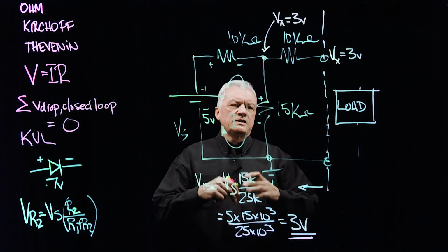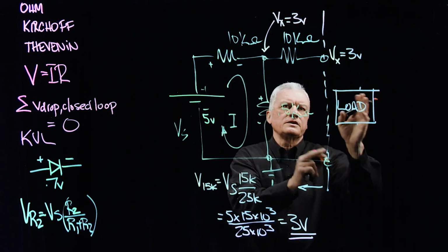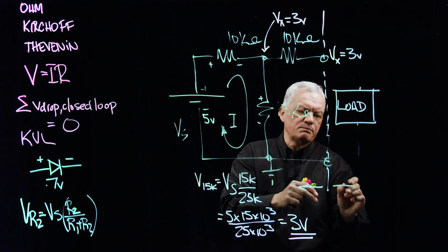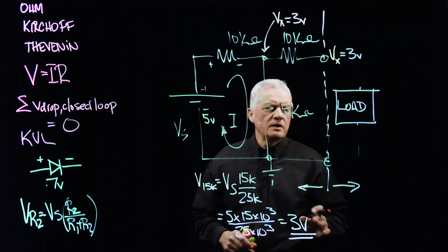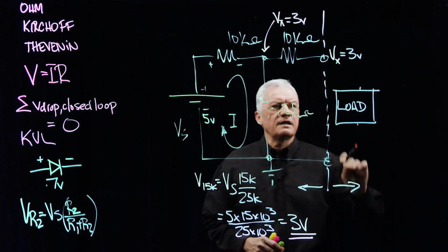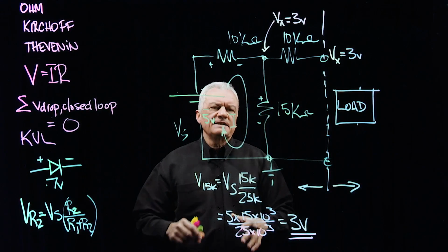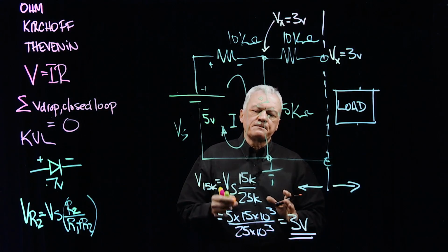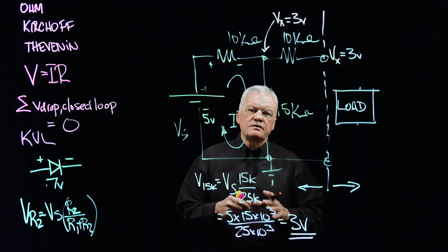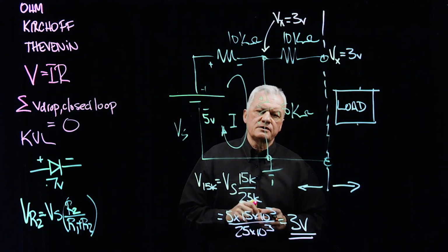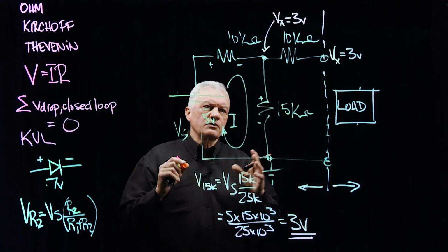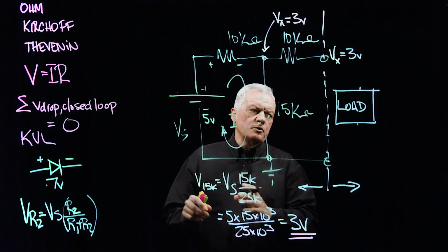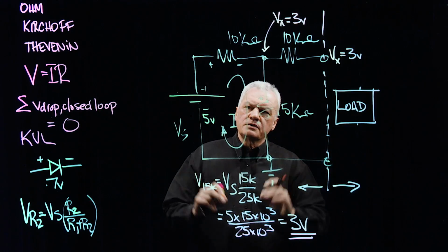He says, it's one thing to know what is the voltage presented outside of this black box, okay? What is the voltage presented to the load outside of this black box? But internal to the box, there is an internal resistance. And as current is drawn, there will be a voltage drop across the internal resistance. So what he tried to do is create a model of not only the voltage source presented to the load, but also the internal resistance.